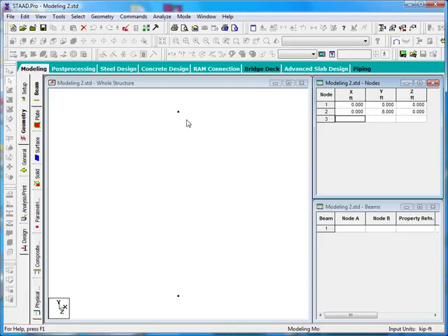The other coordinates are 7, 8, 0. Here's the third node appearing. And then finally we need to enter a 7, 0, 0, so there's 7 and it's automatically 0, 0. So now we can see that we have the 4 nodes that will form the corners of the same braced frame that we created in the previous exercise using graphical methods.